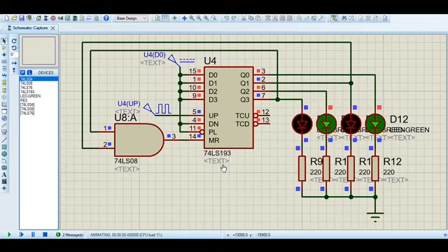Because in the entire up counting cycle of the 74LS193, it is at the count of 10 that these 2 pins would output 1 at the same time. And so we can use that case to check for a count output of 1, 0, 1, 0, or binary 10. So as you can see, the count output here still counts from 0 until 9.